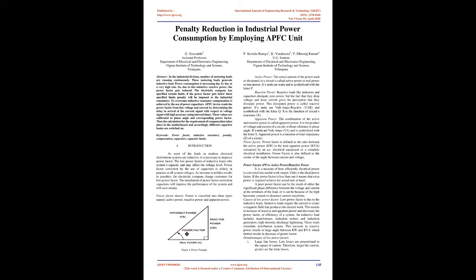Reactive power. Reactive loads like inductors and capacitors dissipate zero power, but the fact that they drop voltage and draw current gives the perception that they dissipate power. This perceived power is called reactive power. Its unit is volt-amps reactive, VAR, and it is symbolized with the letter Q. It is a function of the circuit's reactance, X.